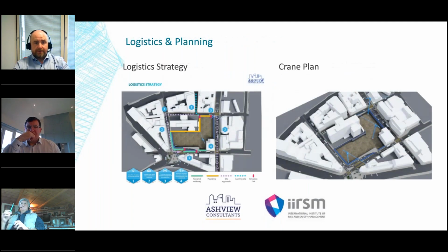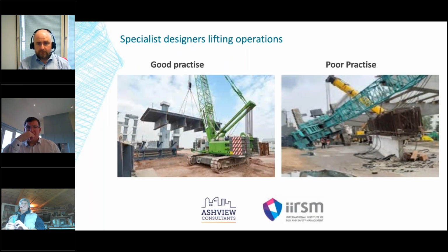So as you mentioned, Paul, the design of that piling mat underneath that crane or piling rig is fundamental to make sure we don't get what happens on the right. And that's not just the ground conditions, that is the design of that mat that's been designed by a structural engineer or a temporary works engineer. And it's often thought, oh, that's just compressed earth. No, that is an aggregate, it's a platform, and it can be 2-3 meters deep on very difficult sites. And that is often completely misunderstood, and we end up with what's on the right there as a consequence.